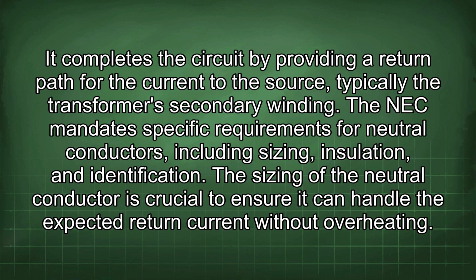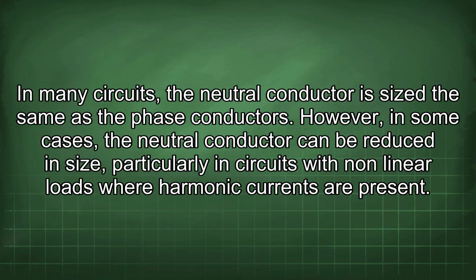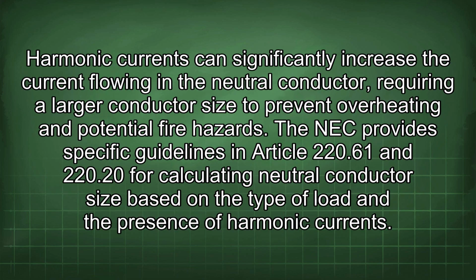The NEC mandates specific requirements for neutral conductors, including sizing, insulation, and identification. The sizing of the neutral conductor is crucial to ensure it can handle the expected return current without overheating. In many circuits, the neutral conductor is sized the same as the phase conductors. However, in some cases, the neutral conductor can be reduced in size, particularly in circuits with nonlinear loads where harmonic currents are present. Harmonic currents can significantly increase the current flowing in the neutral conductor, requiring a larger conductor size to prevent overheating and potential fire hazards.